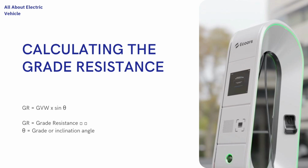To calculate the grade resistance, we simply multiply gross vehicle weight by the sine of the angle of inclination of the road surface. The grade resistance is typically given in units of force such as newtons or pounds, as I have explained earlier also. The grade resistance can be affected by various factors such as the weight distribution of the vehicle, the speed of the vehicle, and the road surface condition. Therefore, it's important to consider these factors when calculating the grade resistance for a particular vehicle and driving condition.